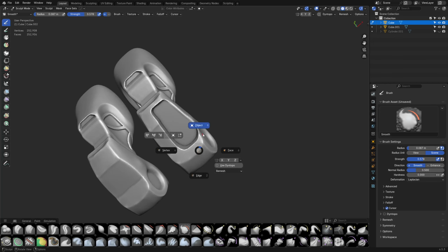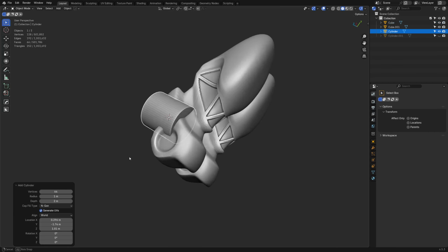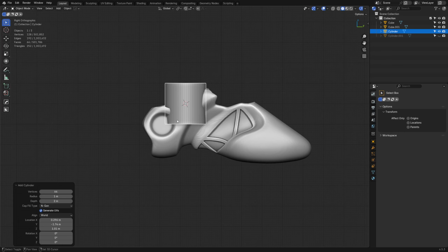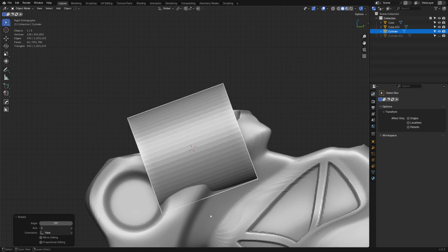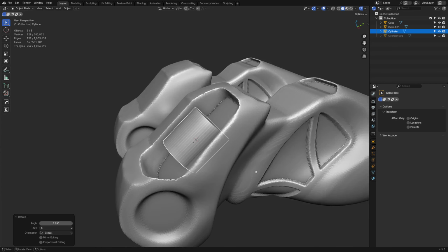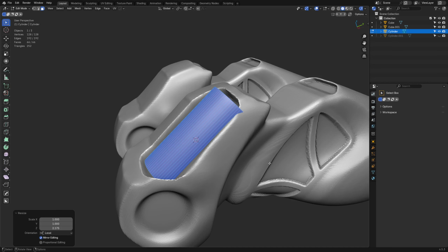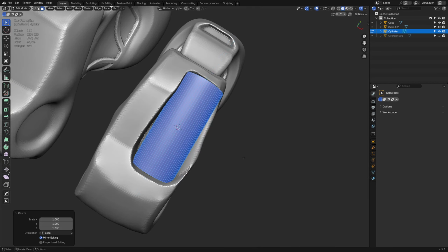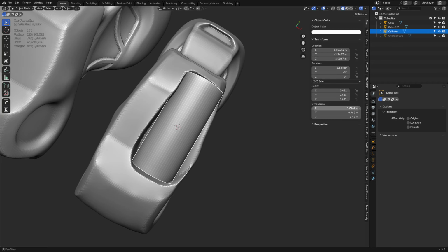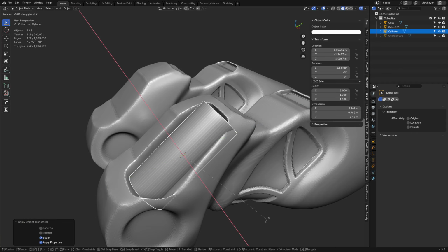Now, I was going to put a cylinder in here. I don't think that even fits in that shape like that, but let's try it anyways. So, kind of view from this side, and we'll try that. Add a little bit, R and X. So yeah, we can go into edit mode and scale on Z twice, get it in the right area, the right shape. We want to make sure that we don't do the scales, right? Apply scales. The rotation should be fine. For the most part, I think this is okay-ish, but it's just a little too far in, maybe.